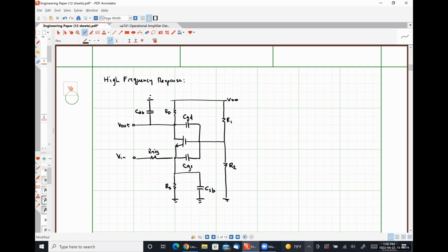All right. Okay, so this circuit can be simplified to some extent because I agree with what I think most of you are thinking right now. Oh, good God, this looks terrifying. Okay. So one of the biggest simplifications that we can make to this is by understanding what's going on at this node, our gate. So what's going on at this node? Is a voltage divider circuit. You're absolutely correct. So is this node at a DC quantity?